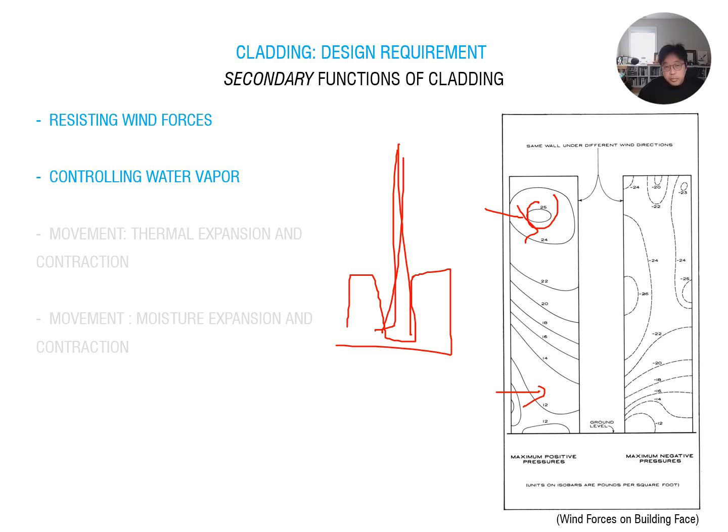And next, you have to consider controlling water vapor. Water vapor occurs through possible condensation. You already talked about it, right? This happens from conduction, the main reason for condensation, but it can cause loss of insulating value, metal corrosion, and wood decaying. Also, you can see mold on the surface. That's why you have to consider controlling the water vapor.